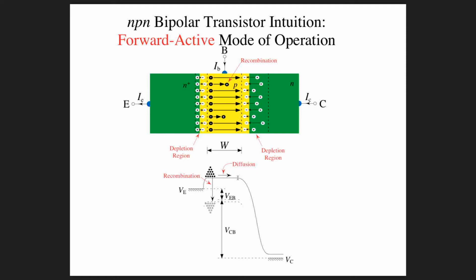It's going to go from being negligible compared to the concentration at the other end of the base, the emitter end of the base, to something that's even more negligible compared to the concentration here. So it's effectively like I'm subtracting zero from the concentration of electrons here at the emitter end, and that zero isn't going to change anything if I make the collector voltage bigger.